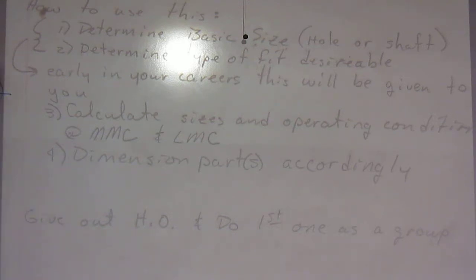I wanted this to kind of look like a drafted drawing. Let's do it this way. So this would be plus 0.006 minus 0.001, and my diameter is 0.690. Okay, and that might be your ended drafted drawing. We would still need this dimension here also, correct?